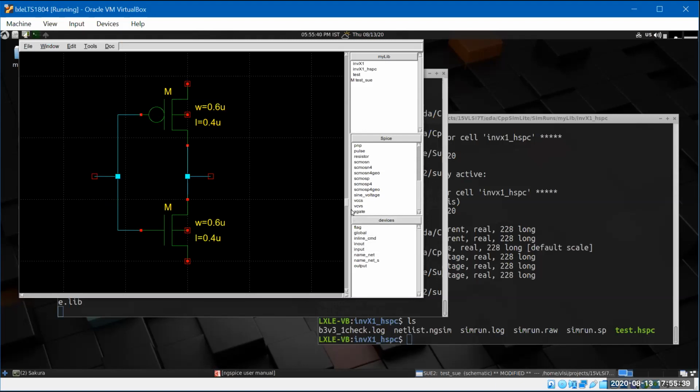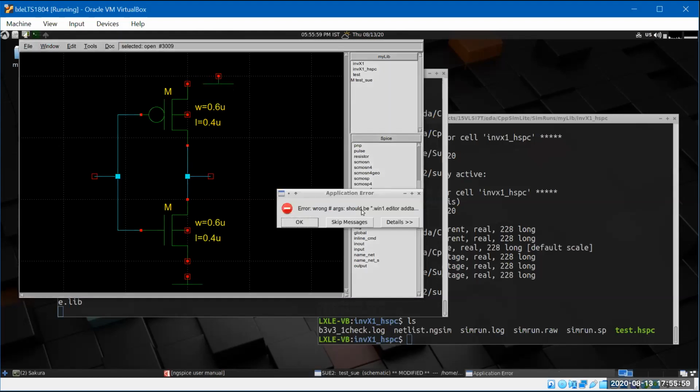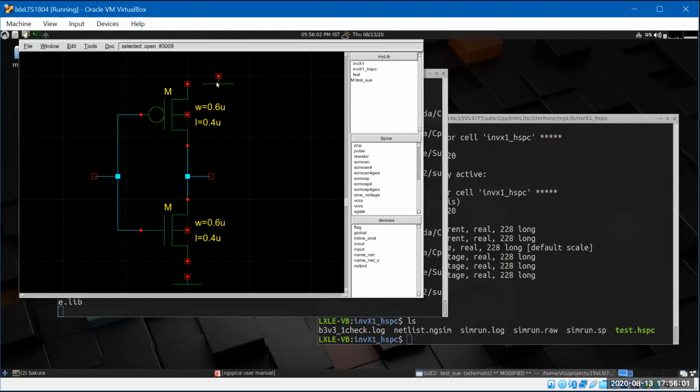Now you can choose the global symbols. So if you choose the global, again, shift left key, it brings in a global. So you can put one global here and you can just copy the same global to the VDD and use the R button to rotate it. Oh, it doesn't rotate it. Let's say R. Okay, so you click it and say R, it will rotate it.